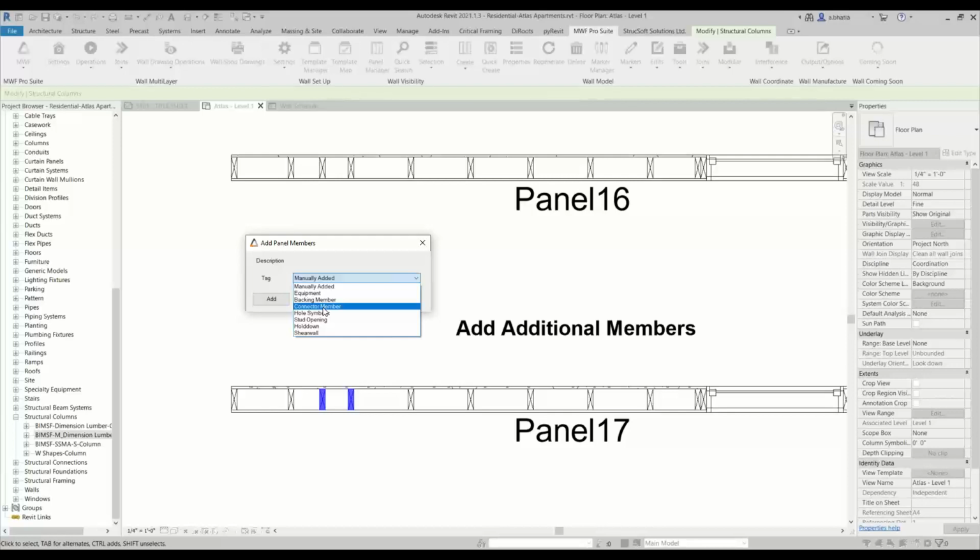So if I was adding a clip to a panel, or maybe my lifting clip to the panel, I could treat it as a connector member. Even if it's clashing against, say, my top track or my stud, I can just say that even though it's clashing, even though validate members is turned on, since I've specified it to be an extra member or connector member, it's not going to delete the member, because in priority sequence that member has no priority.